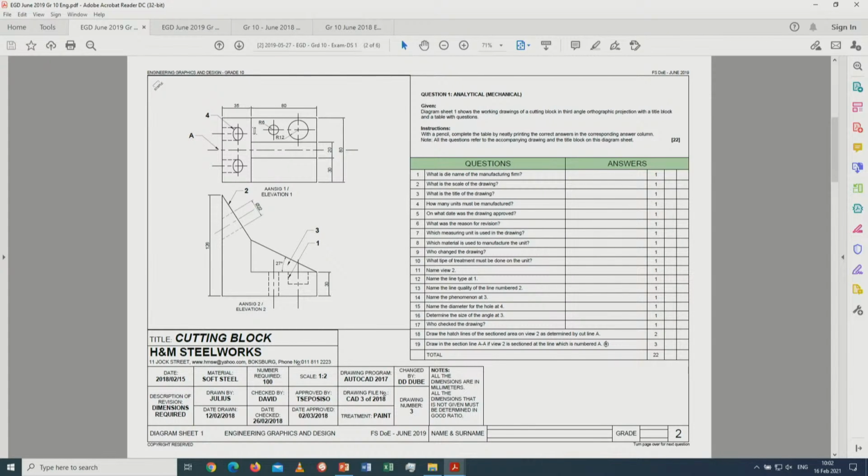It points out to you a drawing. It's giving you the 2 views of the drawing. Now we have to determine if it's the top view, the front view, front view and the top view. Now remember that this is third angle orthographic projection. So if that is the front view, this could have been the bottom view, but it can't be, because a bottom view, if the front view looks like that, can't be showing the profile as it is over here.